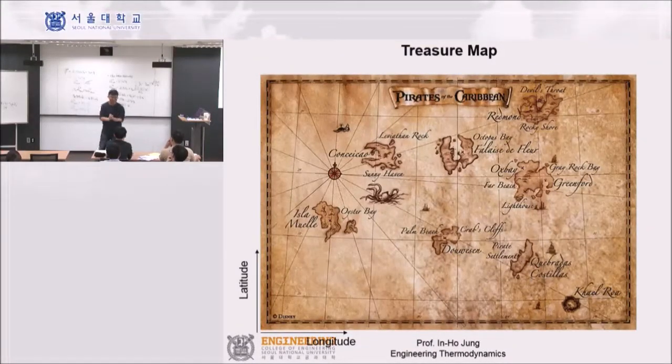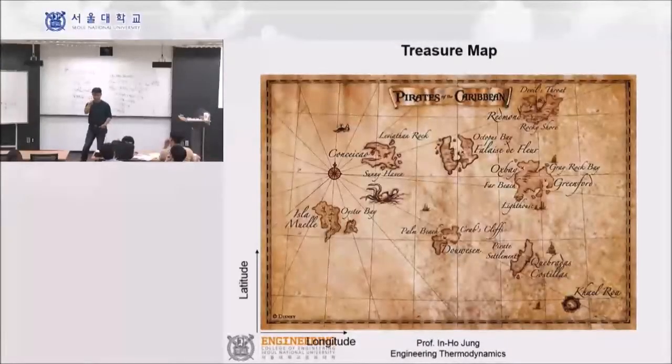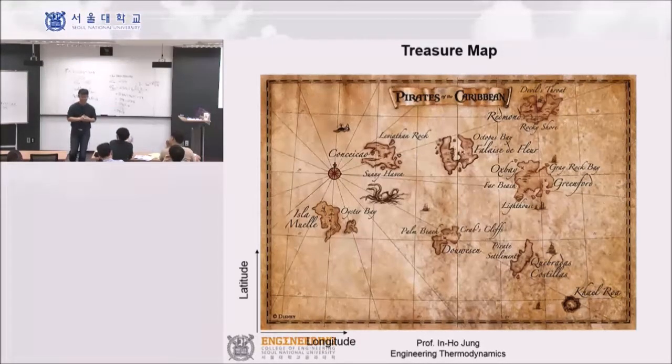This is knowledge you need. And then if you have the phase diagram, you can see where the areas are that you actually want to make. So which composition and which temperature can produce a specific amount of the different phases. So by using the phase diagram, you can find composition and temperature. Composition is like the ingredients, how much of each ingredient you have to put in at the beginning. And temperature is basically processing, the real cooking temperature and cooking hour.